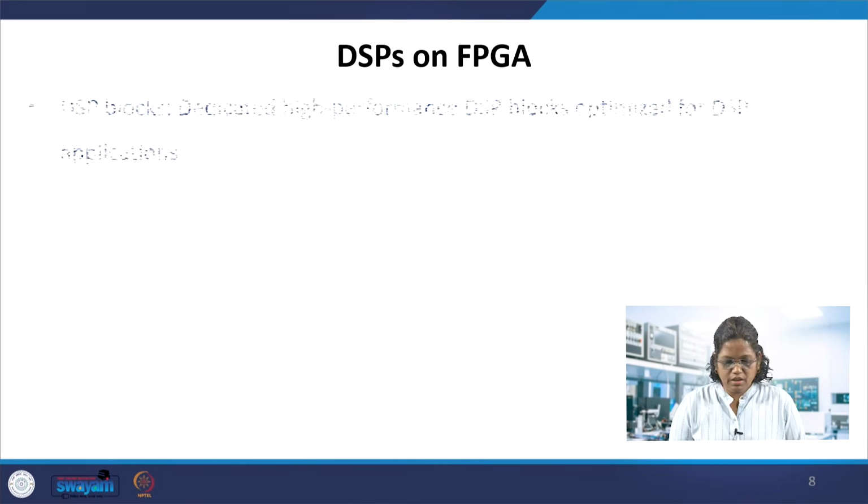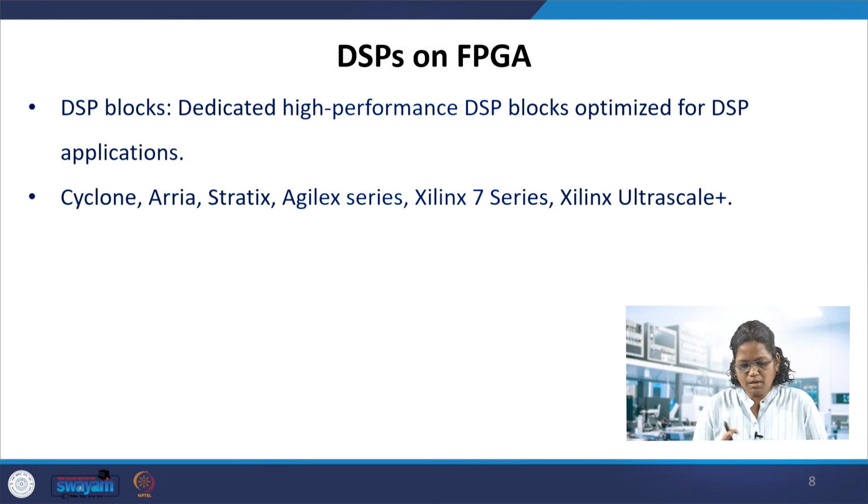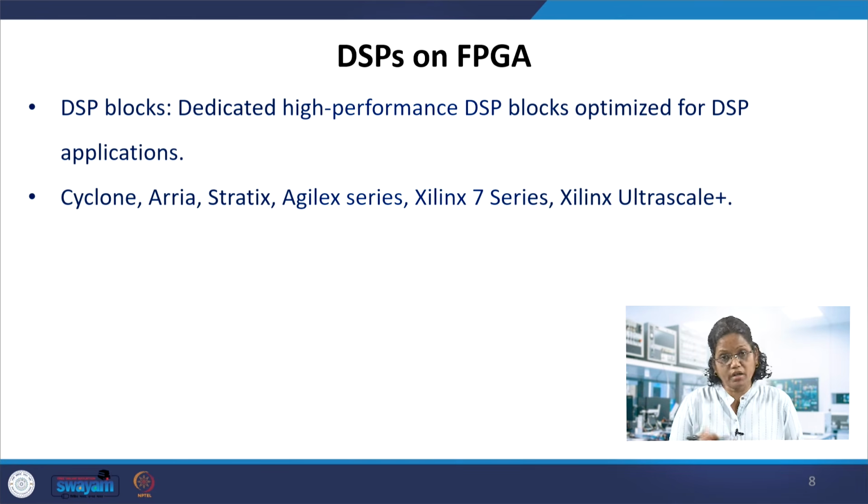The DSP blocks are dedicated high performance blocks, especially optimized for DSP applications. DSP blocks are included in the following series: in Altera, the Arria, Stratix, Cyclone and Agilex series, and in Xilinx, the 7 series and UltraScale Plus all have these DSP blocks.